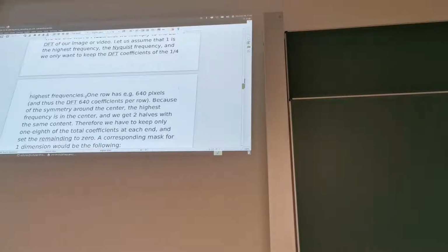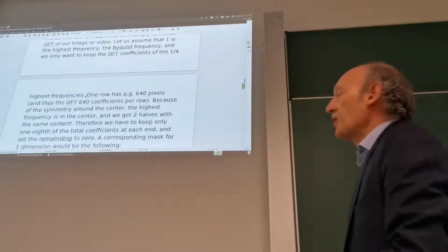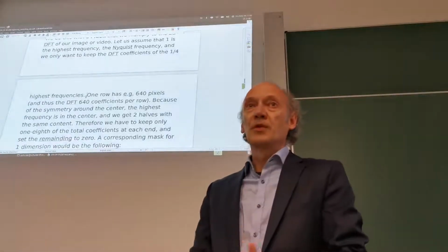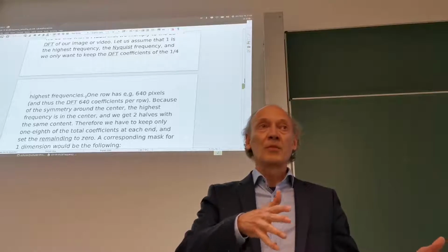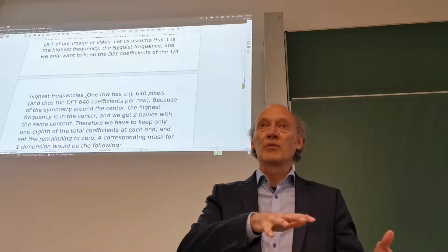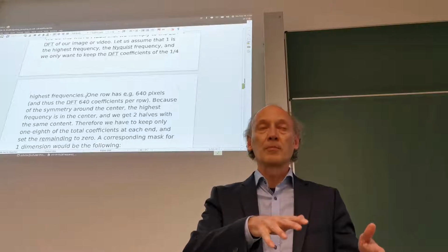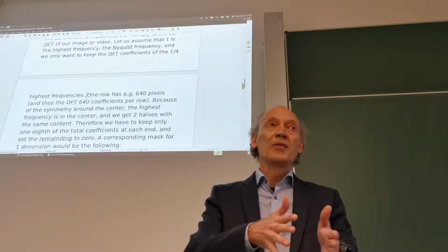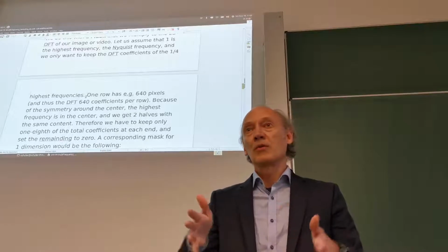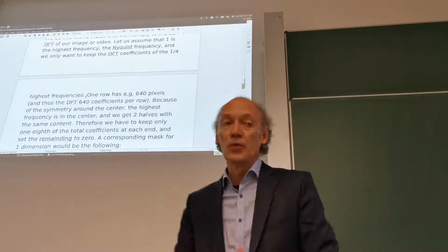So basically, this means we want to downsample by a factor of 4 in this example. Before downsampling, we have a Nyquist frequency which depends on the sampling rate that we use in our system, like the number of pixels per degree. Then we want to do a downsampling by a factor of 4, which means our Nyquist frequency is then just 1/4 of it.